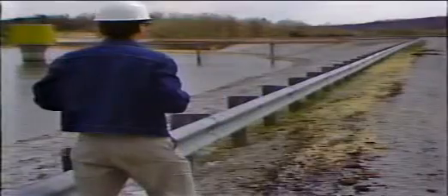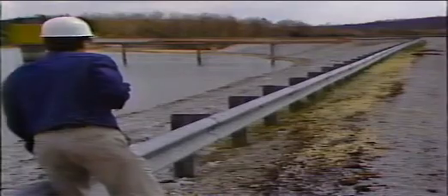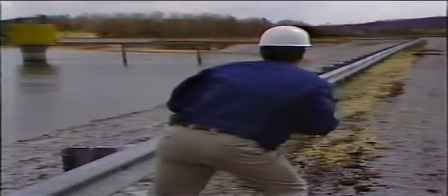Another deficiency, misalignment, can be an indication of structural movement. To spot misalignment on a straight axis dam, sight along a crest linearity, such as pavement stripes, guardrails, or posts. Structural movement of the crest will often be reflected in these features.